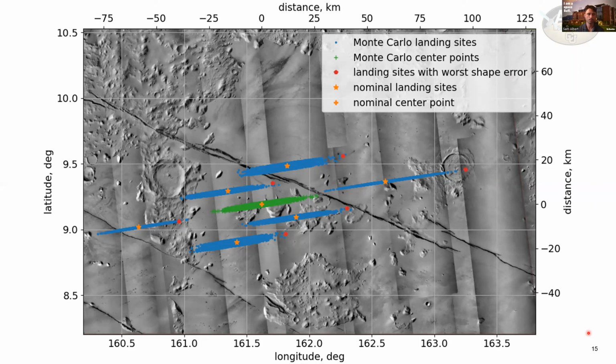between the different probes. The error in jettison velocity is independent for each probe, and that will affect them all differently. But the dispersions on entry flight path angle and entry velocity of the approach trajectory, as well as on atmospheric density, more or less just shifts the network around back and forth in the downrange direction specifically.